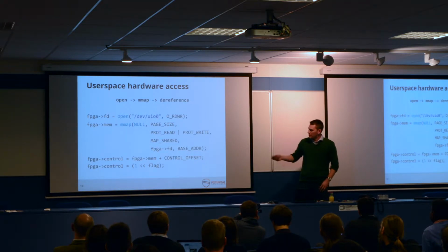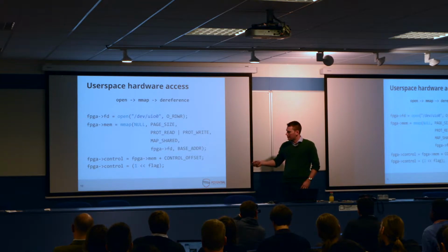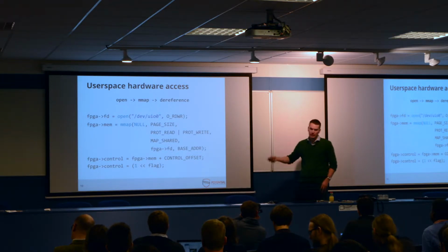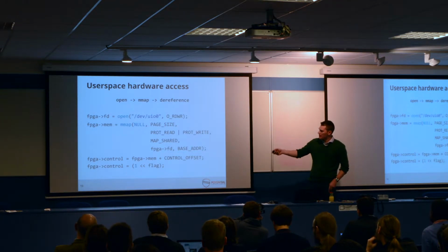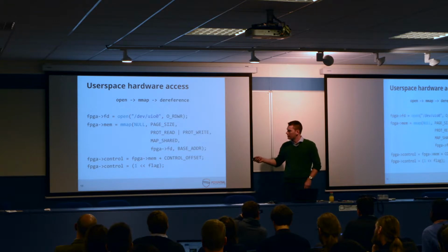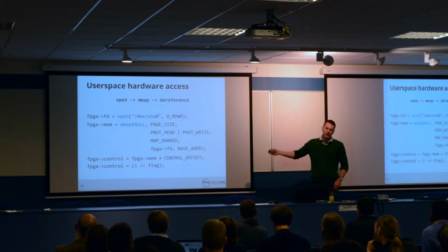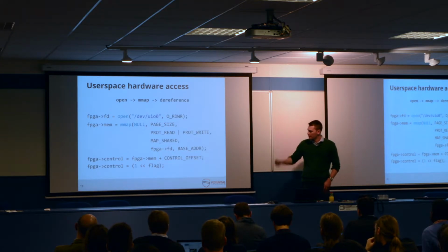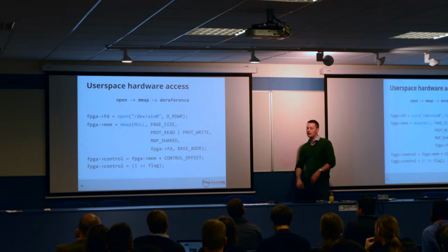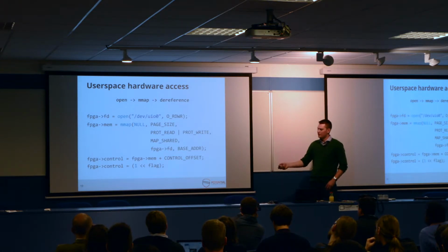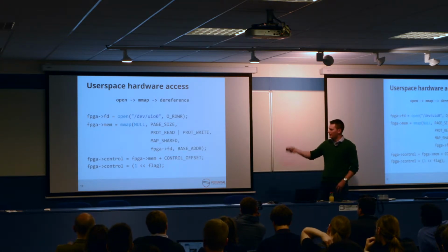And in the FPGA world, a lot of your device access is memory mapped. Some people even use devmem, but you might be using a UIO driver or something, and you mmap your device, and then you've got a memory mapped area you can just access your device directly. Okay, this is quite awkward for co-simulation because obviously it's hard to execute this software in user space without having some kind of package.